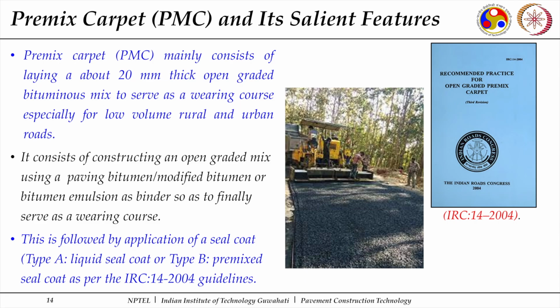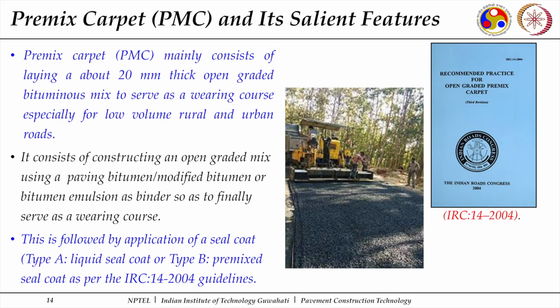So I can apply bitumen emulsion at ambient temperatures without heating it, because it has low viscosity at ambient temperatures. If I use a paving binder, I have to heat it so that its viscosity gets reduced and I am able to mix it. Then once this open graded mix is laid, it is to be followed with an application of a seal coat. Two types of seal coats are recommended here: A is a liquid seal coat and B is a premix seal coat.